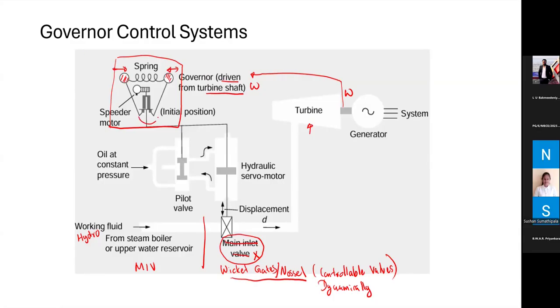So they are rotational on this axis. When they are rotating with the operational speed, if the speed is high, these metal balls will move out, and due to that movement, this particular sleeve will move up. So moving up indicates movement of this pilot valve. So it will be basically moving this up or down, causing a movement of this particular pilot valve in one direction.